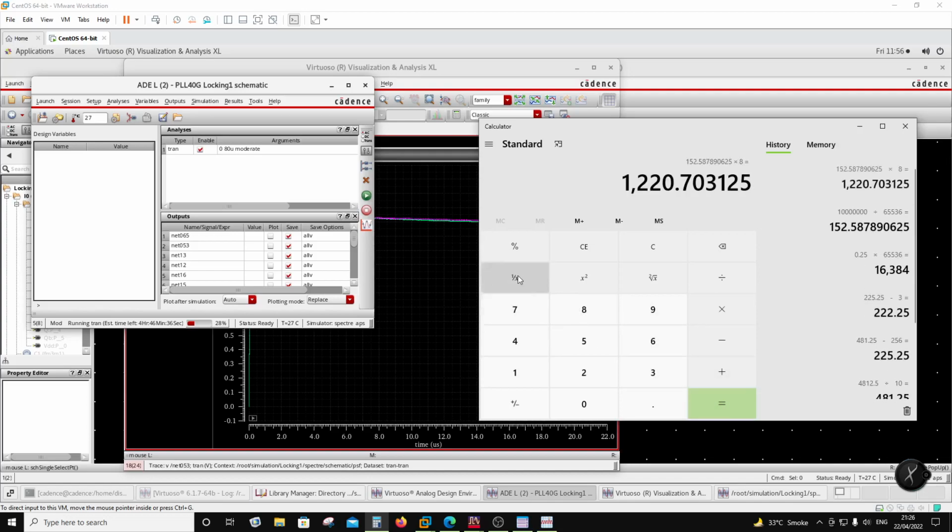Okay, so you are going to have 1.22 kilohertz of resolution. Okay, if you run it for the entire 2 raised to 16, then the resolution you're going to get is 1.22 kilohertz, right? And that's in your 10 megahertz. There are going to be 65536 steps, right? So that kind of fraction you can achieve here, right?